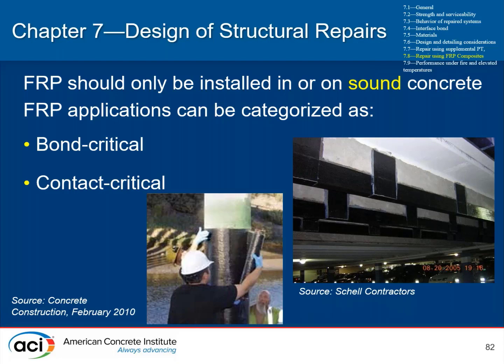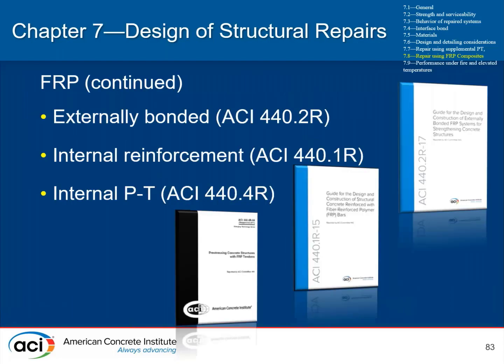ACI has a number of documents that are applicable for the design, including those that address externally bonded FRP, internal reinforcement of FRP, and internal post-tensioning or pre-stressing with FRP.